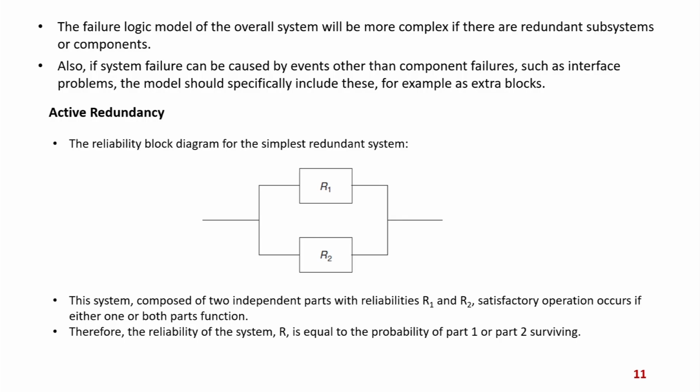Okay. So, now we will consider that practically all the systems will not be in series, there will be some redundant systems. So, we need to modify whatever we have seen, that is, finding the reliability at the system level. So, this is called the active redundancy. Of course, we will use the term static redundancy. Static redundancy means we are not using any switch. As if in the chain both the elements are active, and it is assumed that only when both the systems fail will the failure be there. So, the systems are in parallel.